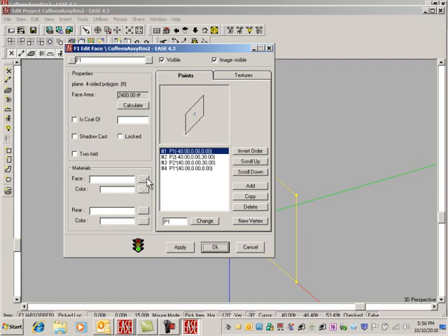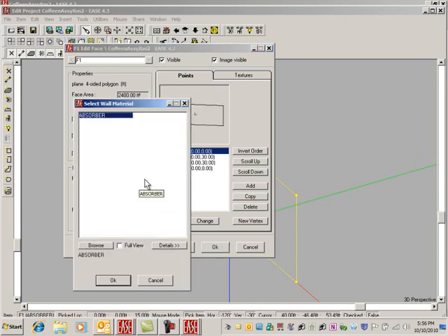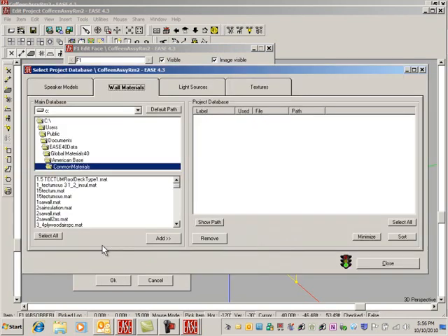Mineral fiber lay-in ceiling board should be, I think it's called lay-in ceiling board. And here it is. Using the control key, I can pick some others and put them over there all at once. Two layers of 5/8 chipboard we're going to use. So I'll find it next. Gypsum wall board, 2 times 5/8. Select it.